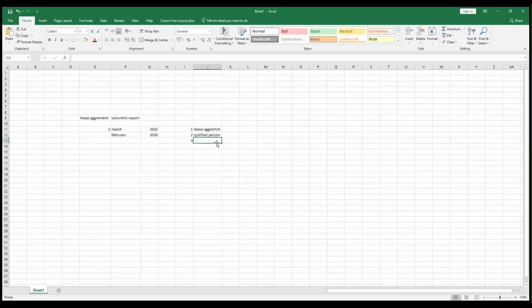The next one you want is your lease boundary, where you might have multiple coordinates, 4 coordinates, 5 coordinates, whatever it is, as per KML or whatever. They will have a boundary pillar actually. This boundary pillar will be of minimum 3 feet height as per standards and should be marked in yellow. This is the standard boundary pillar for the lease boundary. Wherever there is a change of line or point, you will have one pillar which is minimum 3 feet above the ground and fully painted with yellow color. You have to check that and take DGPS readings of it.